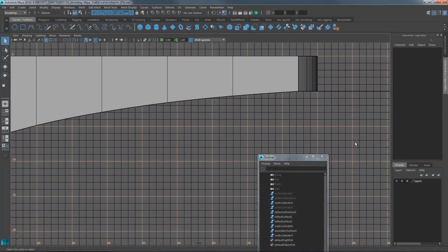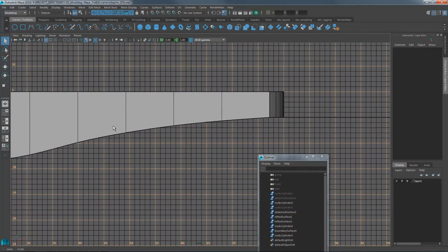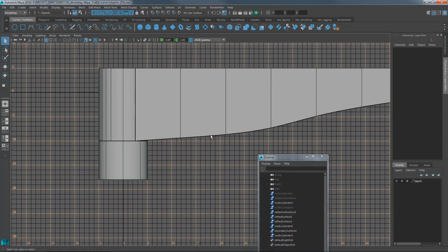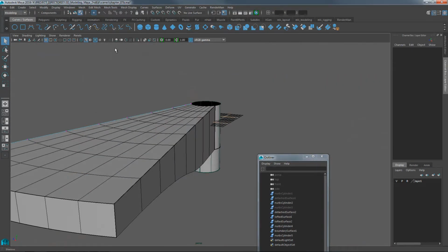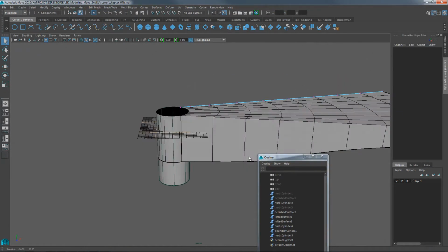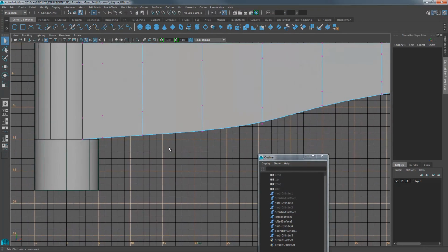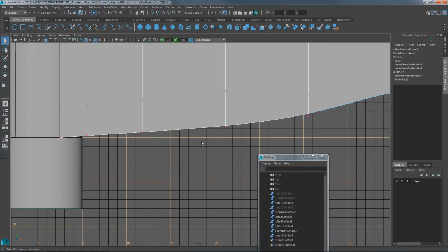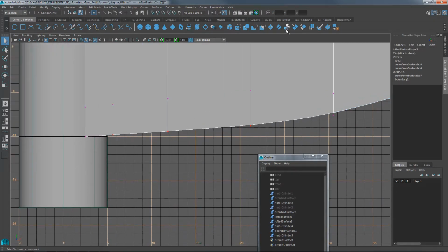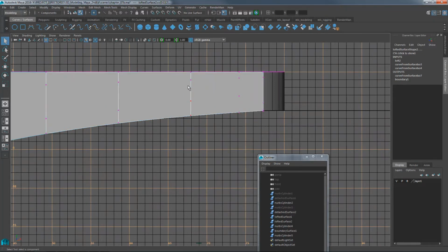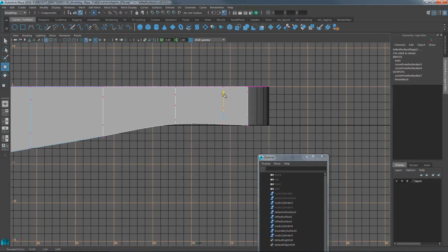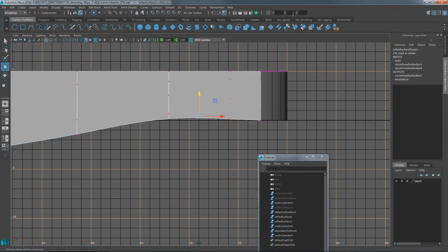I lost a wee bit of the flatness up here and over here in this change. So let's grab CVs again on these objects, selecting these objects, going back to front view and tagging CVs, and I'll set them to an absolute value of -10. So that should flatten out there. And then again up here, just translating those above 0, and then setting them explicitly to 0.